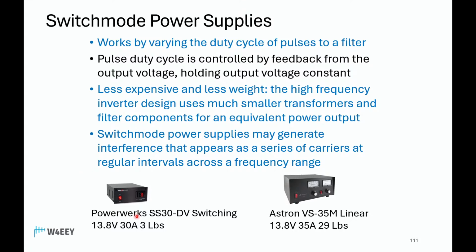You can trust them. So if you have a switch mode power supply that you buy from DX Engineering, it's going to be fine. If you have some Chinese thing, or if you're trying to use a power supply from another source, you got to be careful because that might make this noise. Some hams are strongly biased in favor of only using linear power supplies for this reason. But these work just as well. They're much less expensive, and they're very clean if they're designed for ham radio use.